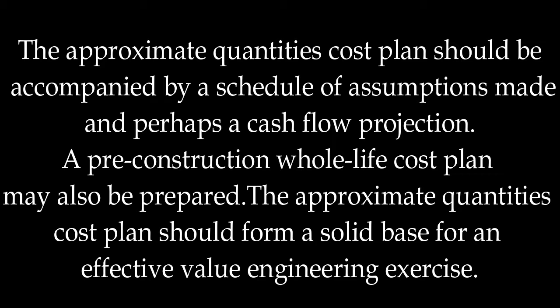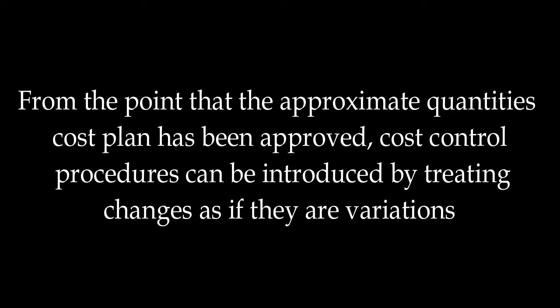The Approximate Quantities Cost Plan should form a solid base for an effective value engineering exercise. From the point that the Approximate Quantities Cost Plan has been approved, cost control procedures can be introduced by treating changes as if they are variations,